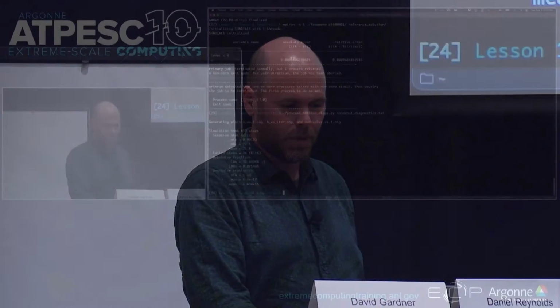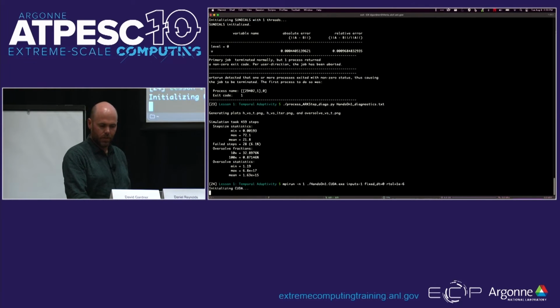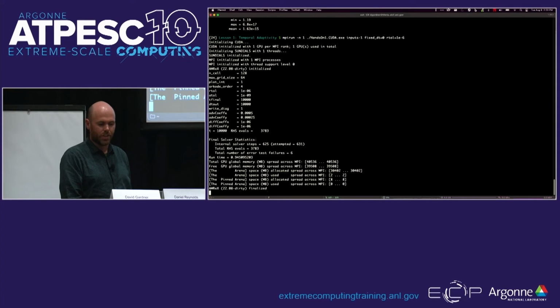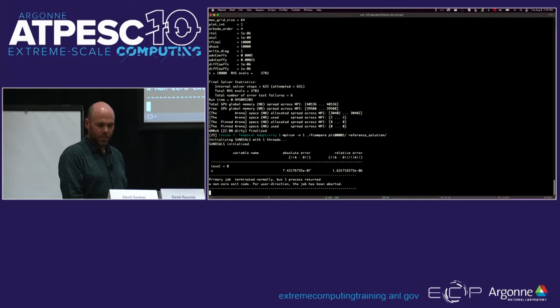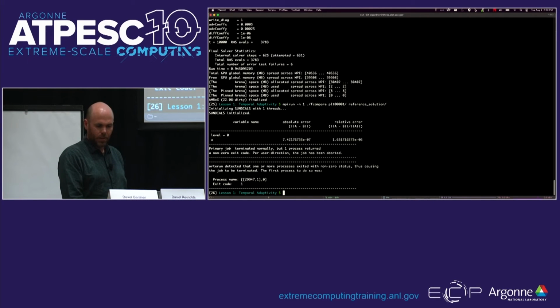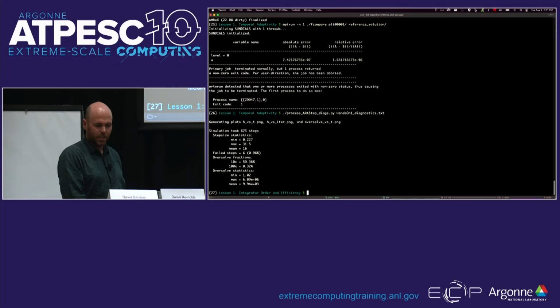We've got smaller oversolve, roughly bigger time steps at some point, because we're asking for less accuracy than we were before. Similarly, if you do a tighter tolerance, it's going to do more work, more right-hand side evals. And then generally the error is on the order of what we're looking for, but a little bit oversolved. And then we can look at stats again. It's taking, on average, a smaller time step size here.